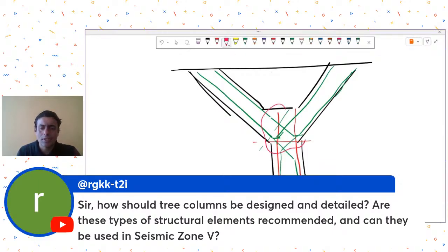Then for this junction, shears and concentrated stresses may be checked, and for that the stirrups have to be accordingly provided. So although I have not provided this type of a column anywhere in any of my projects till now, these are some initial thoughts that I have when it comes to your query.